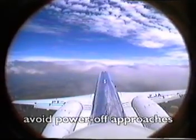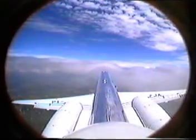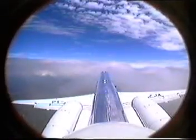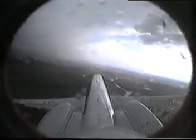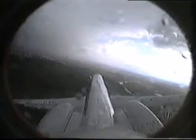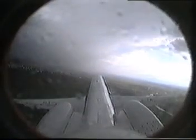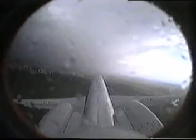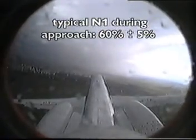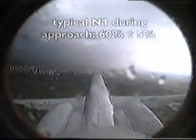Avoid power-off approaches. Recall the poor acceleration response of your jet aircraft and set power with judgment. Anticipate the need for more thrust should airspeed decrease, but don't leave power up for too long or the aircraft will go fast again. Keep thrust in such a value which allows the engine to accelerate to a higher RPM if necessary, and it is also good to keep the airplane in the approach path. In the Embraer regional jets, a typical target N1 is 60%, and if you keep it within plus or minus 5%, it will be good.